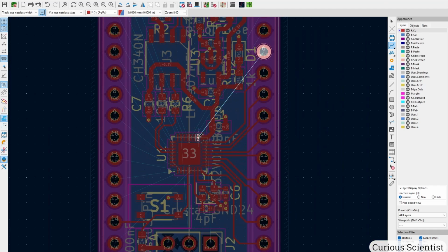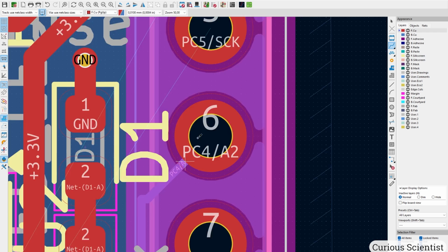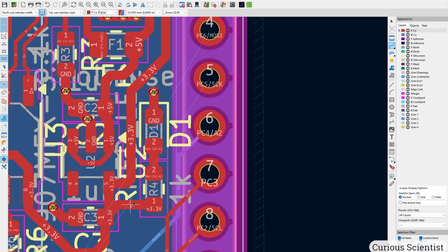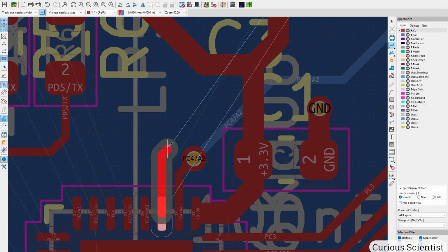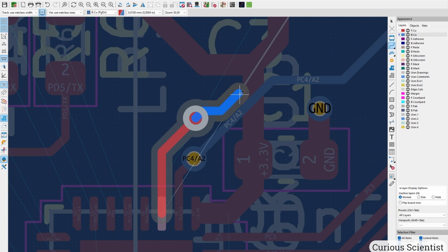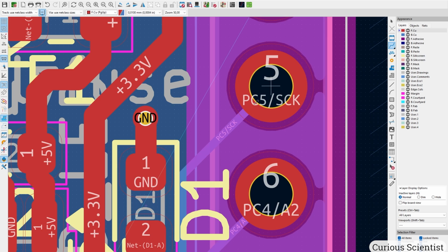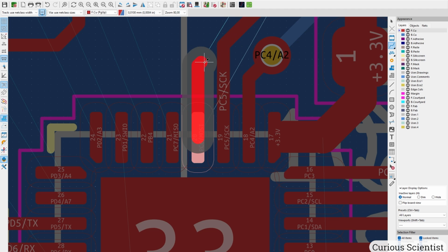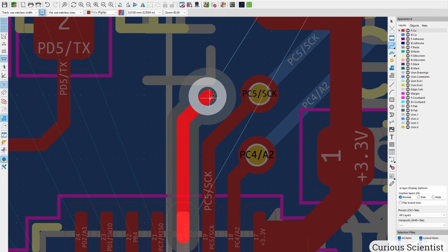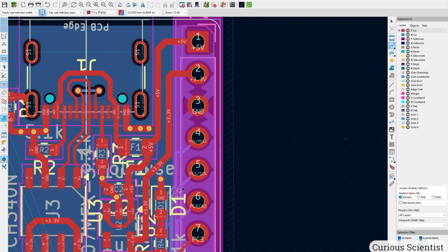And now we are in trouble because this one wants to go up. So press V, and then we go under. And we have the same with the PC5. So we go back. We have PC5. I go up here, press via here, and try to follow this trace closely enough. There. And then luckily we just have one more left, which is PC6. So I place that here, and then I just follow everything here, and we have arrived.